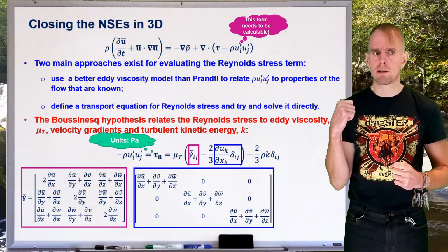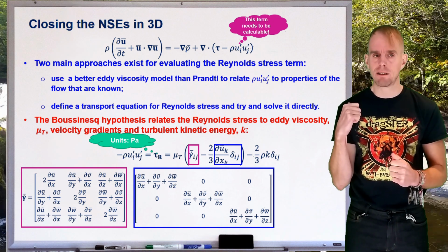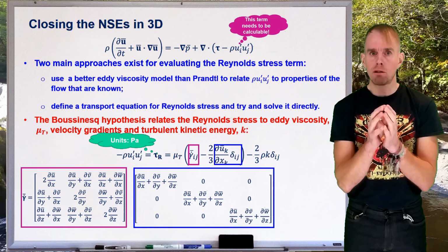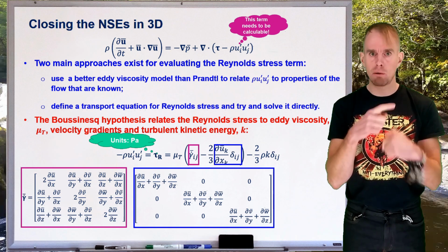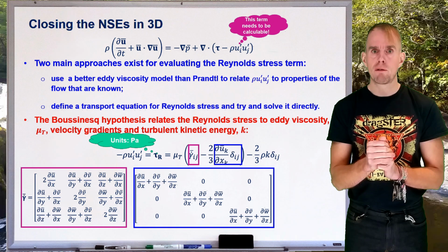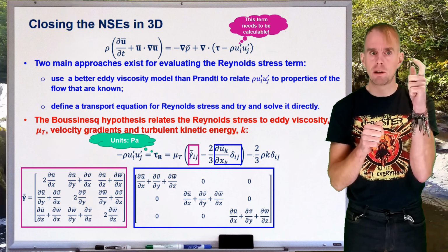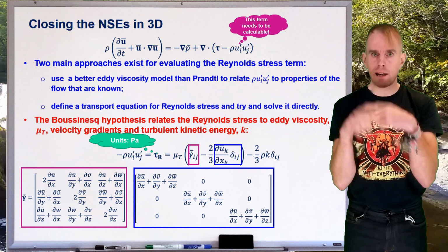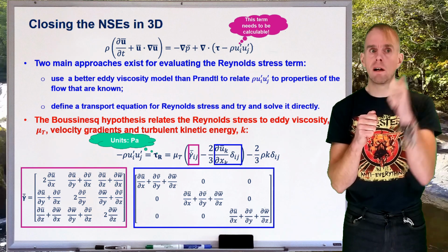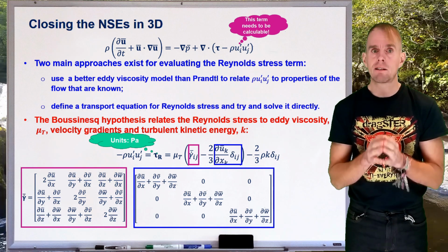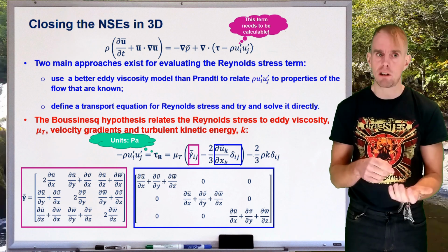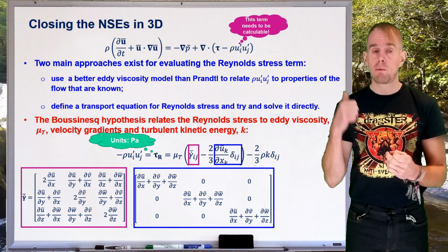Now we can see from the result that the continuity equation only appears on the matrix diagonal. That's where delta ij comes into play, because you're multiplying that continuity expression that you evaluate in that inner loop by a value that delta ij takes. If we start counting when i equals 1, j equals 1 and k equals 1, we count up from k equals 1 to 3 in that inner loop, and that's multiplied by whatever value delta takes when i equals 1 and j equals 1. We're defining delta ij to be equal to 0 when i doesn't equal j, and to be 1 when i does equal j. And so when i equals j, we have continuity.